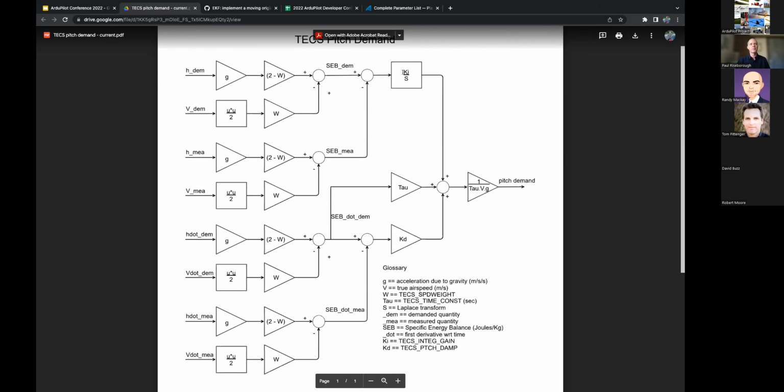And that integrator, this is just a control systems symbol for integrator. I won't explain. Unfortunately, it's what's called a Laplace transform. I'm sorry, the tool didn't enable me to put in a proper symbol for an integrator block. So anyway, this is our TECS integrator. It integrates that error, and the integrator winds up until it hits the limit, and it holds at the limit. And then you climb up, you climb up, you climb up, you reach the height, and then it starts overshooting the height.